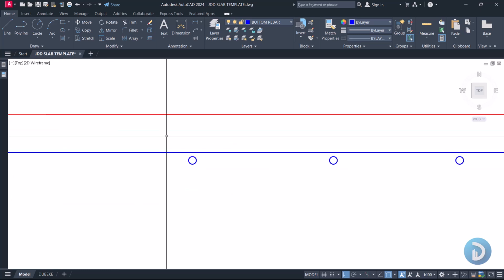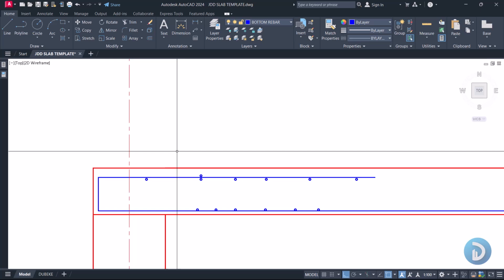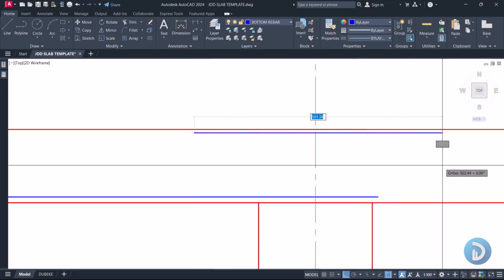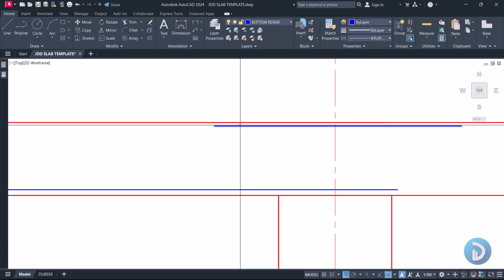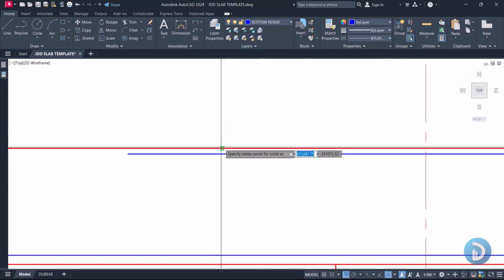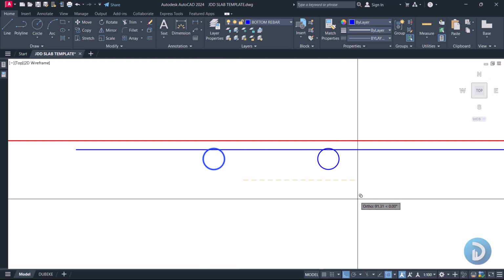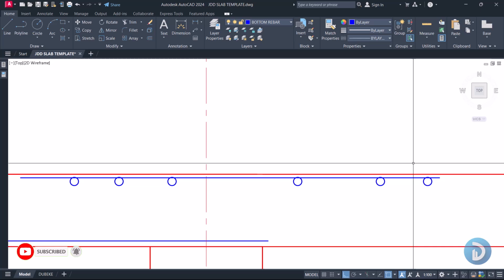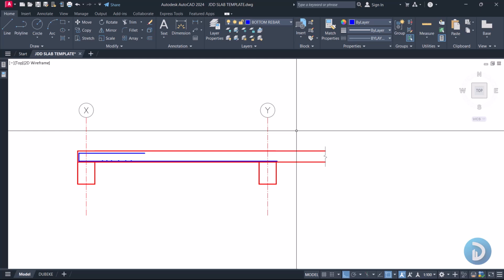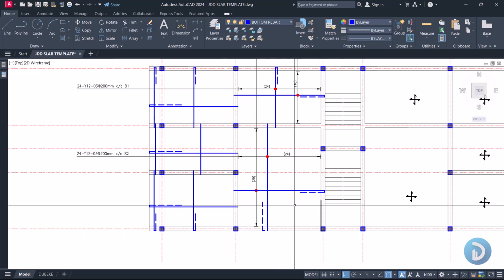Okay, so there will be need to provide another layer of top reinforcement. It all depends on the arrangement around that area. With that understanding as well, when we provide a top bar at this other zone, at this zone where we have the maximum negative moment for our slab, there will also be need to provide another layer of reinforcement that will hold this top reinforcement in place. So this will now need us to create our top bar layer 1 and our top bar layer 2. So let's come over here and begin the introduction of our top reinforcement.